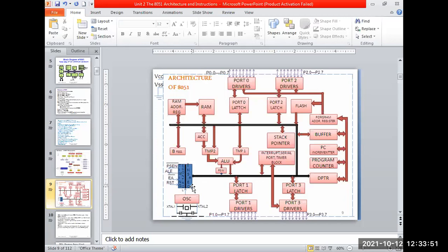How are the three connected? Series or parallel? So 3 and 5 become 8, and 8 is in parallel with 4. The two currents will be different, because this branch and this branch are parallel to each other, but the current through 3 and 5 is the same. 3 and 5 are in series, so that is plus 8. 8 is in parallel with 4. I will mark the direction here.